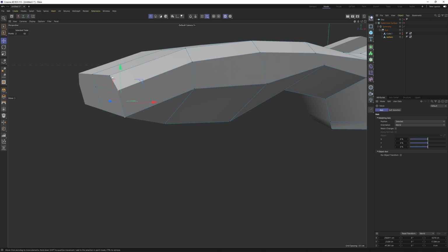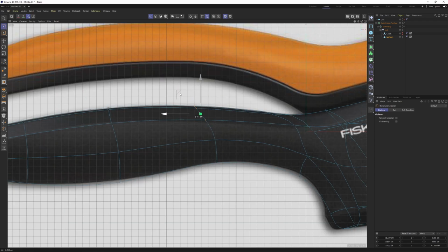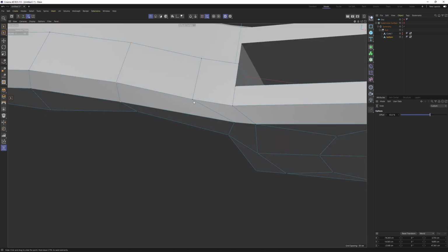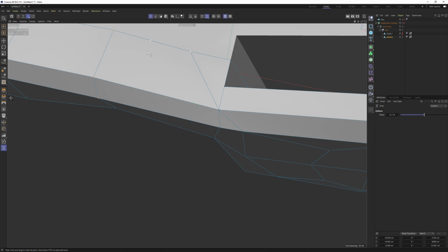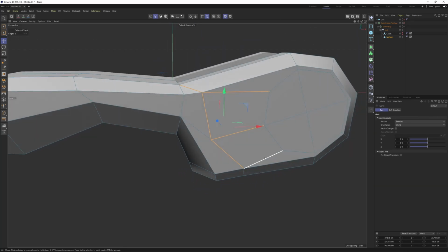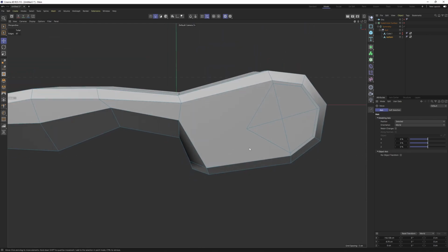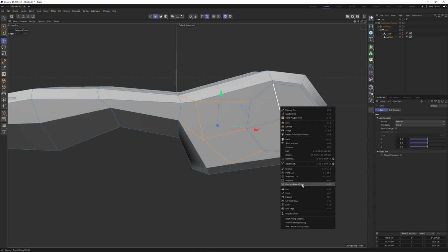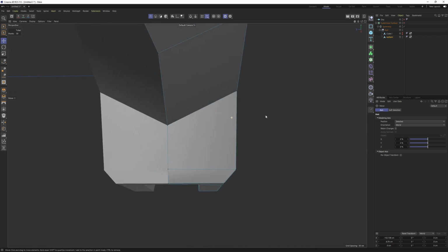Then here, I'm gonna select them all and move them here. Press Q. I think I can get rid of that edge. Points mode, press Ctrl. I cannot slide it here, so I'm gonna go here, then dissolve. For here, let's make a quick cleanup. M and N, dissolve. Then same here. Oh no, actually I should melt them instead of dissolve. Melt, so that I can keep these points. Can delete that point.